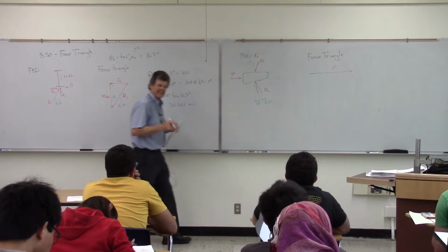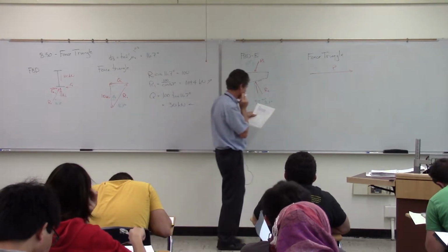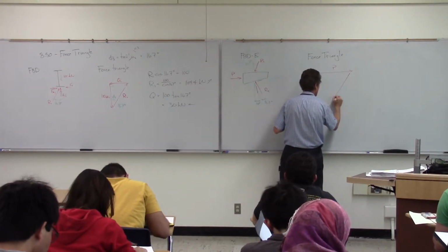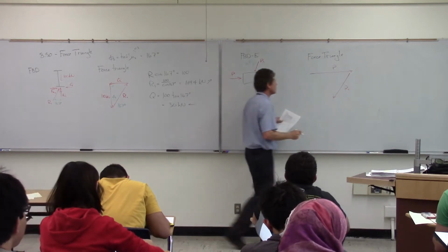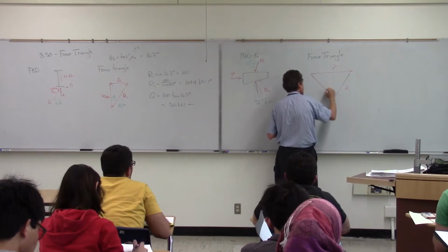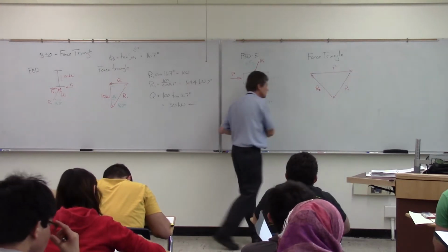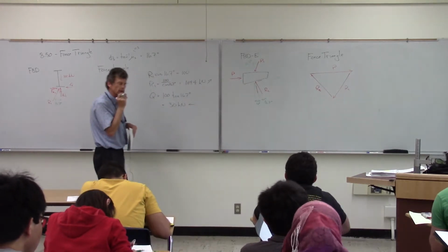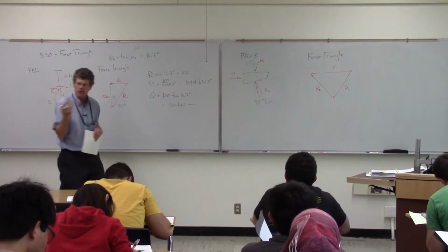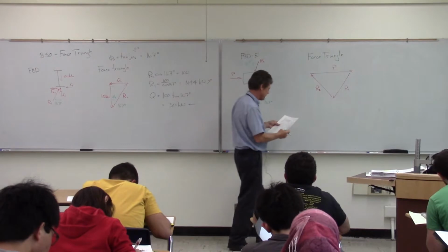Okay, our one easy force to draw in there is going to be the P, which is horizontal. R1 will be like so. And then R2 needs to bring me back home. Unfortunately, we don't have any perpendicular angles here, so we're going to be resorting to law of sines or cosines, which means we need to calculate those interior angles.